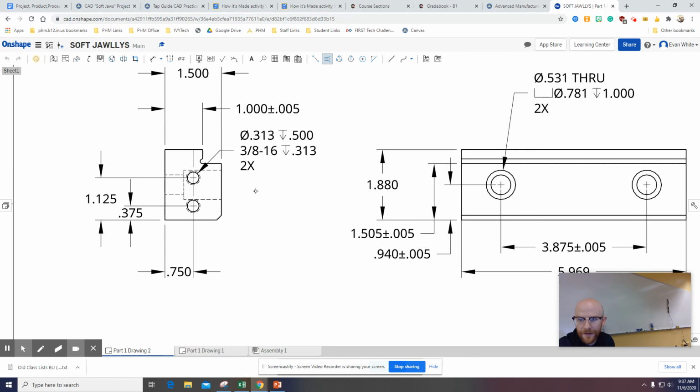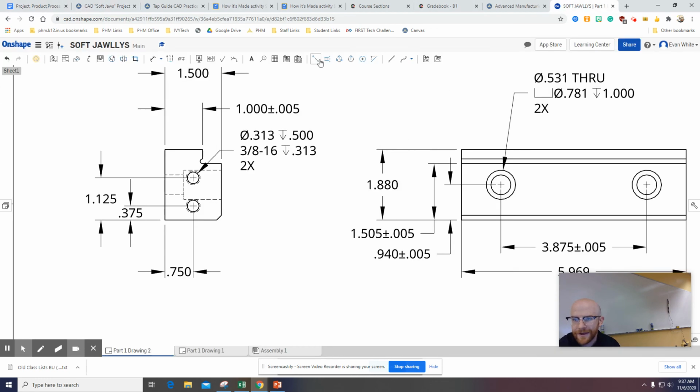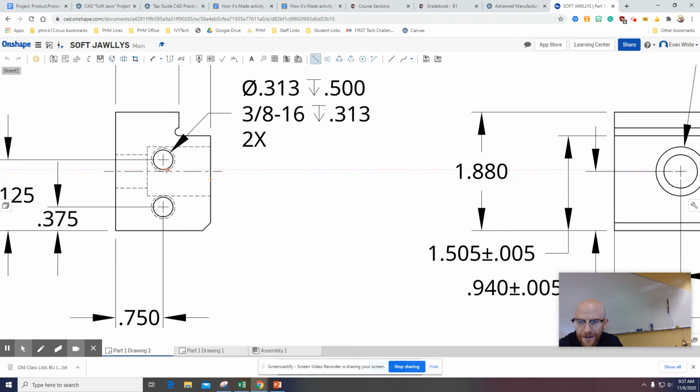So I'm going to undo that. Well, I thought I was going to undo that. Click on it, just delete it. You could have done that, but if we look in CAD, this thing extends beyond it. So I'm going to just do my own. How I do that is I go to the 2-point center line. I'm going to click the triangle on the side of this one. That means it's the center mark of that line, which is the full length, so it should be completely centered. Click across, and now I have a center line in there.